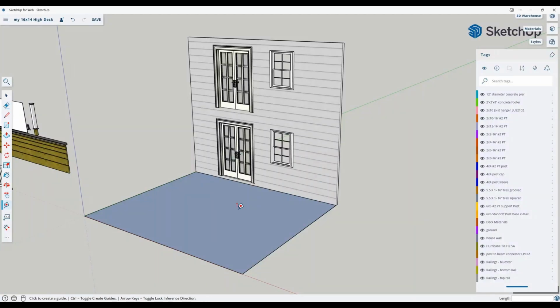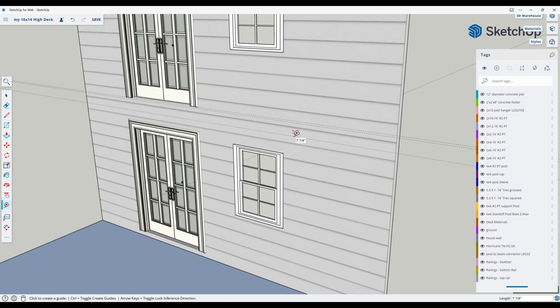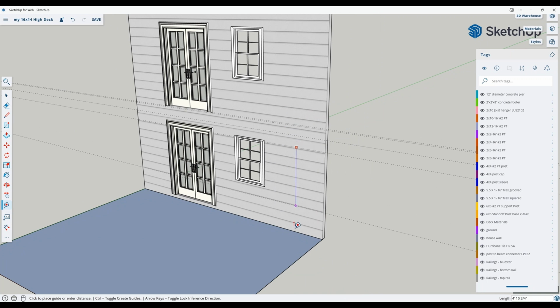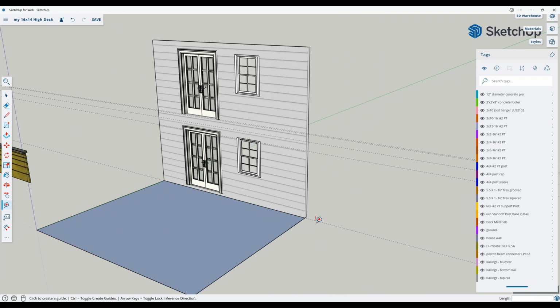Chalk lining is a crucial step in creating building drawings once the reference objects have been determined. In this exercise, we assume the floor level is set at 9 feet. This will serve as the initial marking, followed by these steps. Mark the ledger board line, positioned 1 inch below the floor level. Mark the beam line, located 9 1/4 inches below the ledger board line.